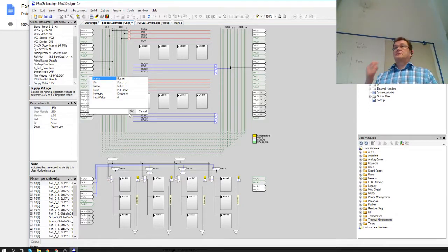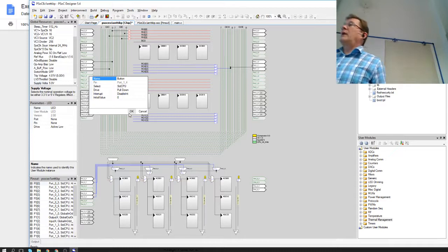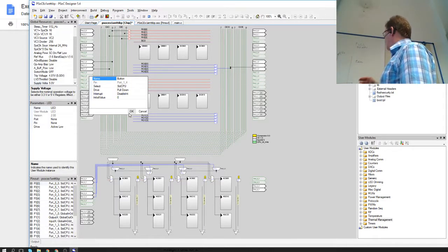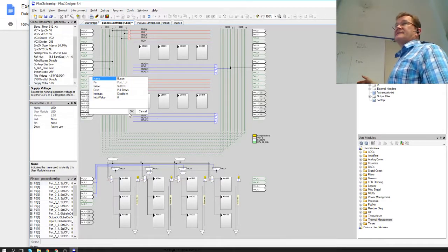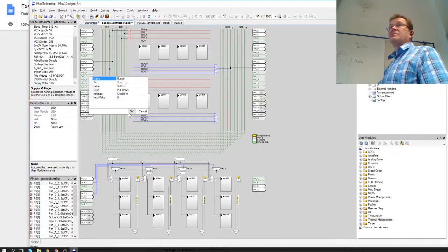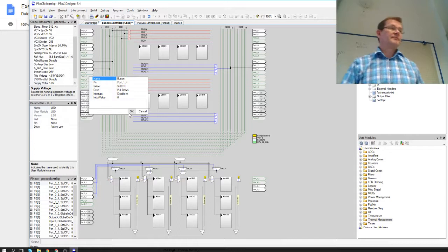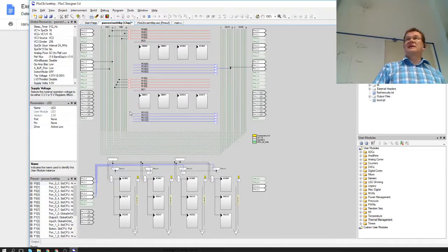So descriptive name for the input, and then drive is pulled down. The other way around would be to have this pin as high Z and have an external pull down resistor. This is more efficient. It doesn't take any resources either.